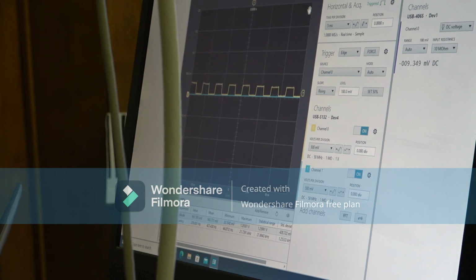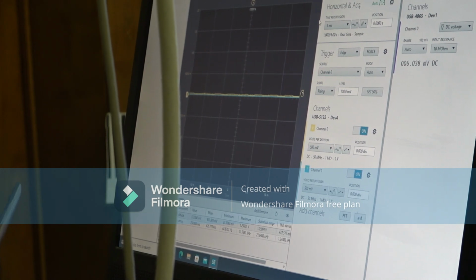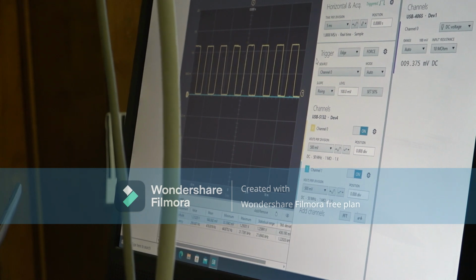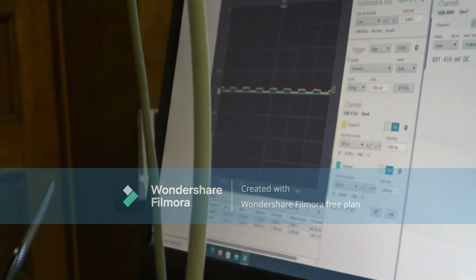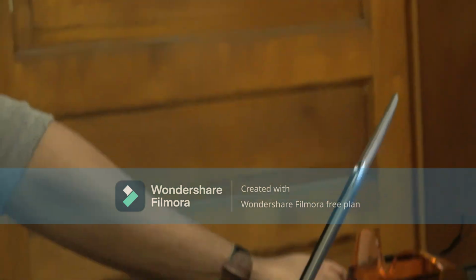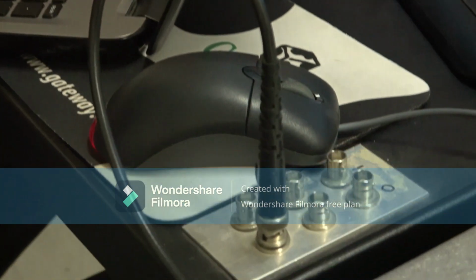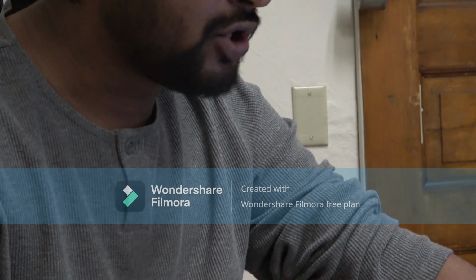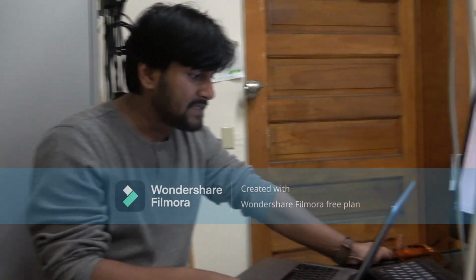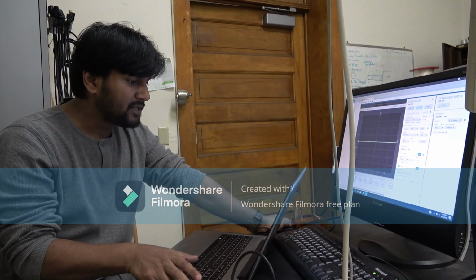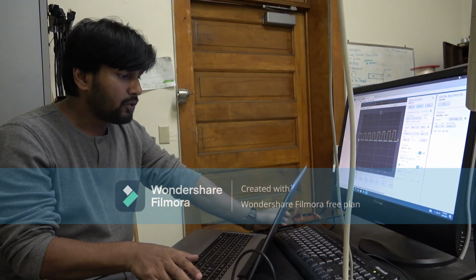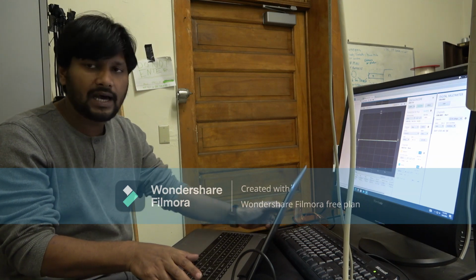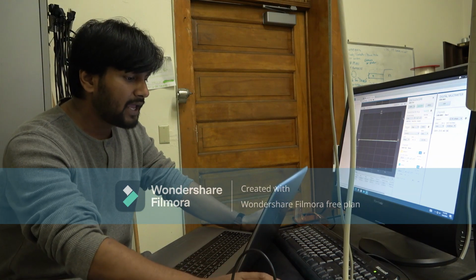Now we will see how to adjust the phase between the chopper and photodiode signal. For this, the components include the chopper control, computer, oscilloscope, and the optical chopper control. The purpose of it is to synchronize the signal from the chopper and the photodiode, and this is done by connecting the chopper and photodiode to the oscilloscope and adjusting the chopper position. The two signals are made to overlap, ensuring accurate measurements.